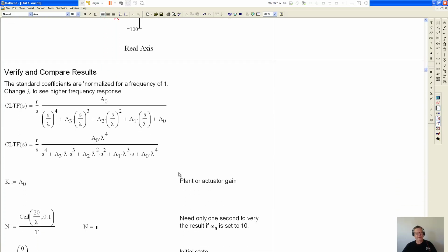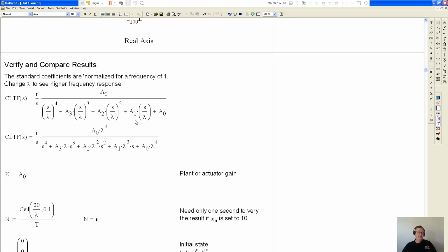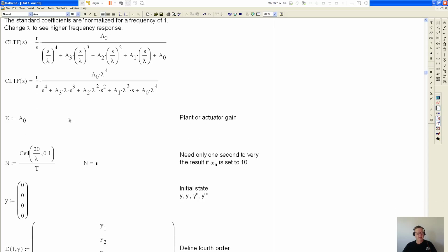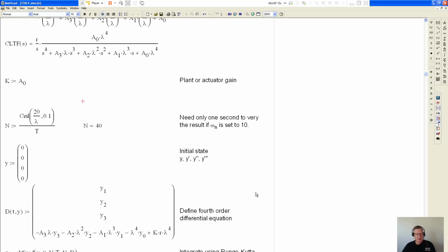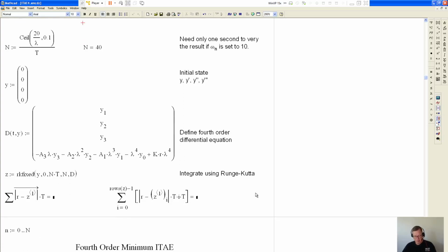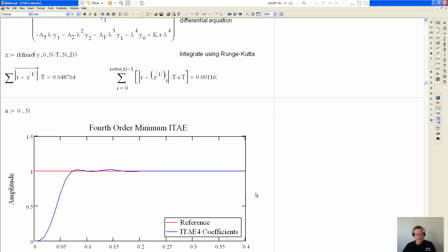Now we're going to see the time response. What I have is the closed loop transfer function plus the step, that's R over S, and I'm going to plot that out. I'm going to do just a few iterations here. There's no need for me to do the whole 60 seconds worth because it only takes about 0.8 seconds to get in position. So you can see we're starting out at 0 and going to 1.